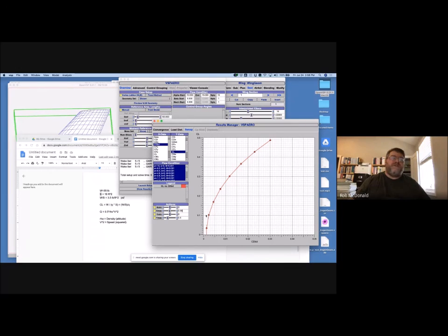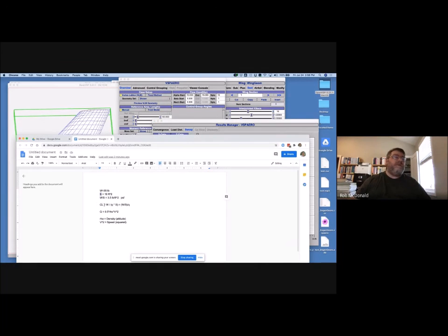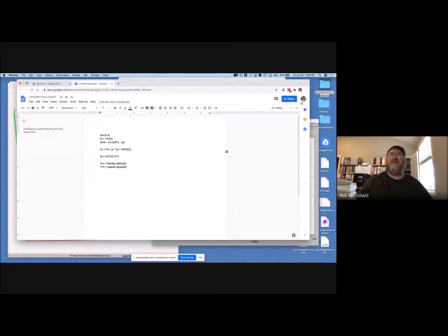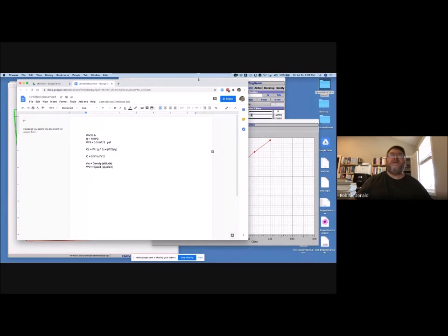So our best range speed, remember I said that best range speed and best endurance speed was a particular speed, right? So they're a particular point on the drag polar, they're a particular speed, and it's only the speed we want it to be if it matches the CL at the wing loading and the speed and the density that we all want it to be. So this is one of those things about aircraft design, you've got to do it all at once and it's all iterative.